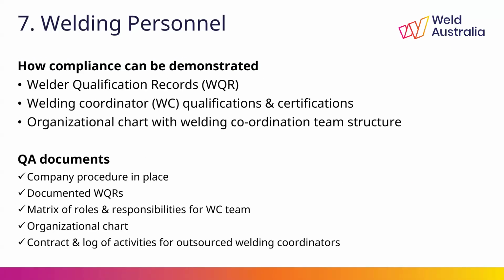Ashkan, sorry, I've got another question. Can the welding coordinator be outsourced for part 2, i.e. a subcontractor? Yes, the welding coordinator can be outsourced. It doesn't matter you are complying with part 2 or part 3. You can have a responsible welding coordinator, let's say external consultant, external welding coordinator.